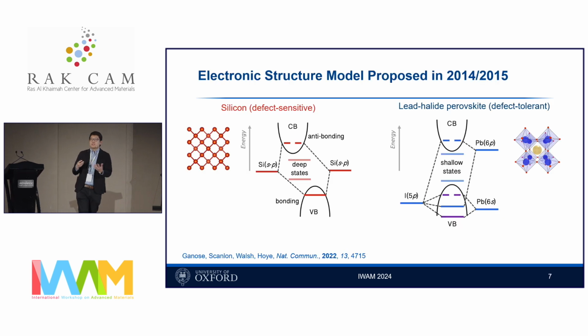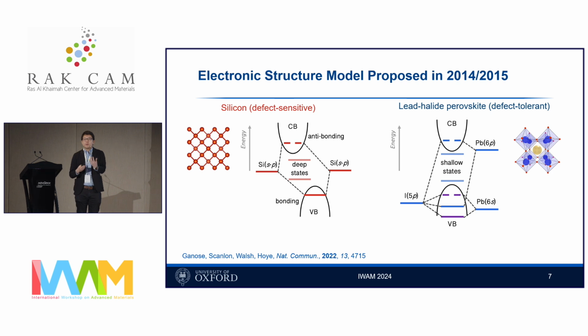So a solar cell needs to absorb light, and it then needs to transport the photo-generated electron holes out of the active layers. So when we think about developing new solar absorbers, we need to talk about the band gap and the absorption coefficient, but we also need to think about the charge carrier transfer properties, in particular, the mobility and the lifetime.